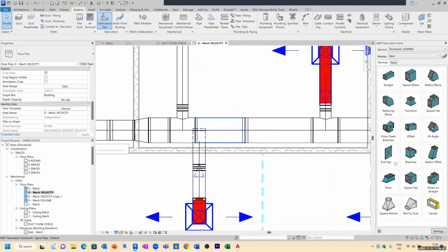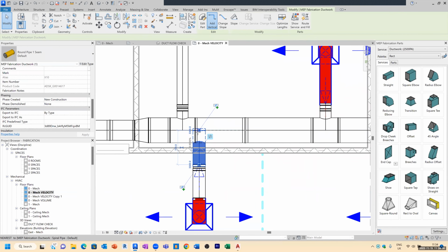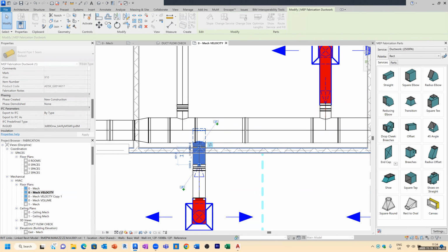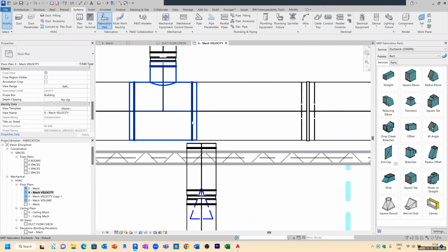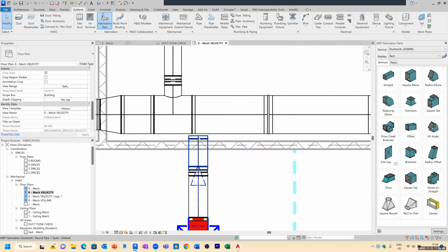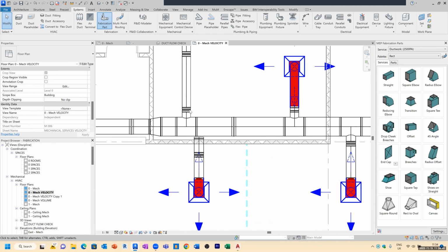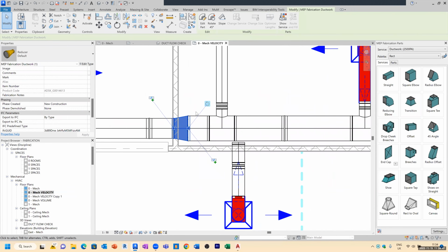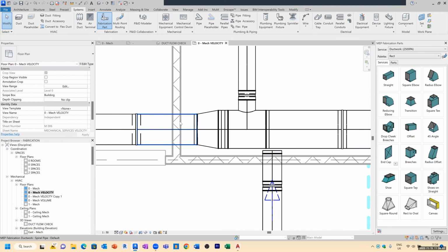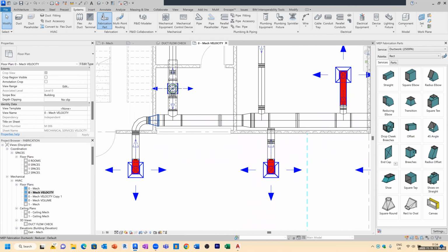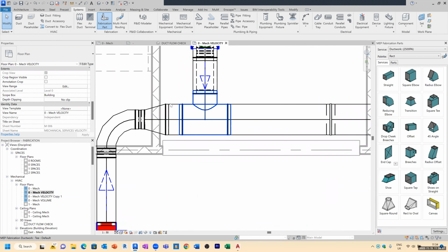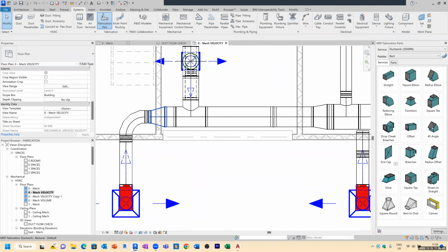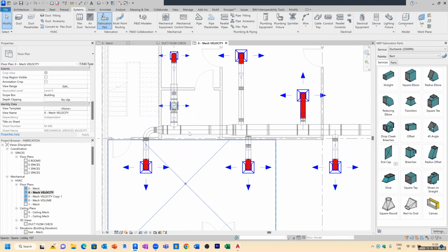And you can see here, there's a bit of an error here as well. We can't add this duct in here because there is a problem with this T-piece in the way. There's no physical space to put a fitting on there. So there's a few things here you have to go around and tidy up using your parts. And maybe here, look, you would move this fitting inboard a bit, and actually only need a smaller hole through the wall there then. And similarly here, you might need to do something to make this hole through the wall a little bit easier to use.